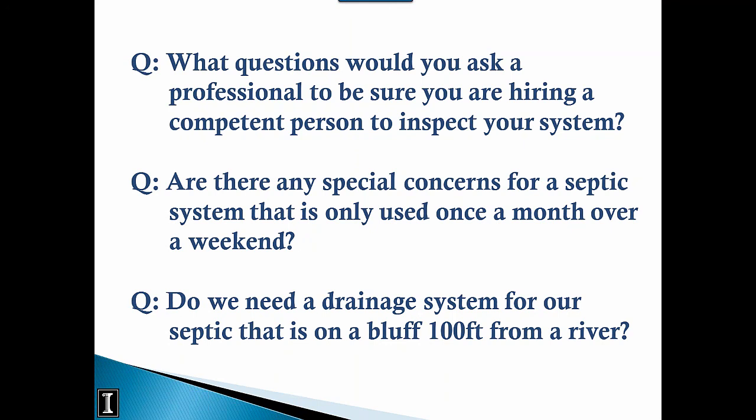There's also what they call a tight tank. It's not an ideal situation, but it's kind of a last resort for a pre-existing structure that's having a septic issue, and it's basically a septic tank without a way out. And there's an alarm when it gets to 3/4 full that will alarm back into the home, and it'll tell the homeowner that it's time to pump, and then at that time, a septic truck would have to come and pump the system. It's not an ideal situation, but it is a situation that I've seen done on a pre-existing structure that just didn't have any other way to meet the current code.